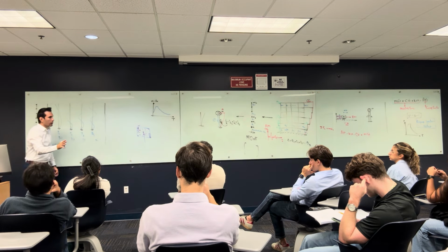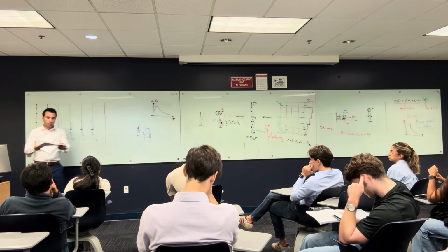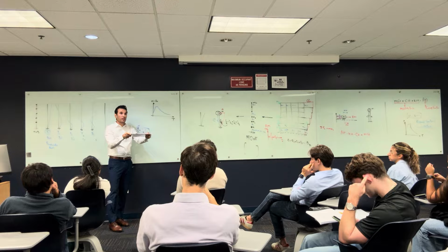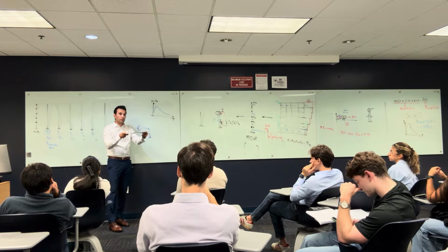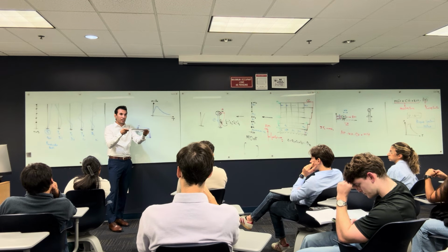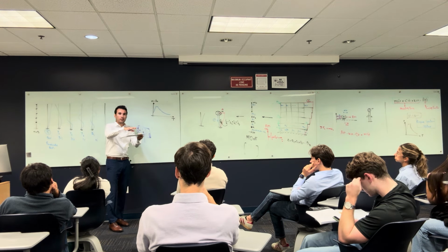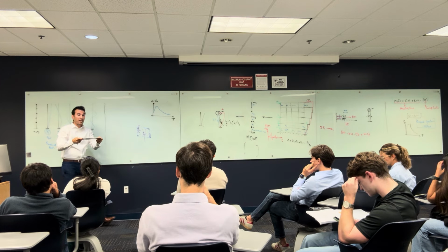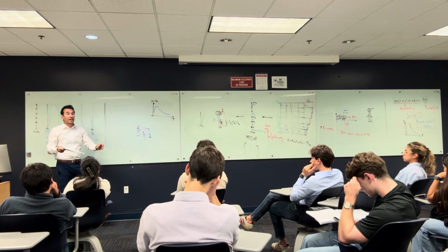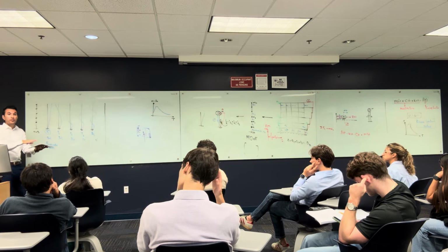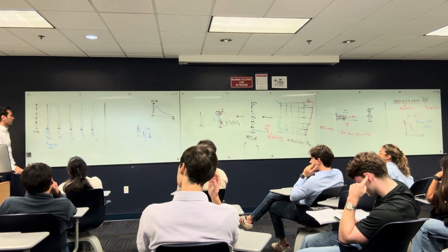And as I told you, usually when an earthquake happens or when a vibration happens in your structure, it's always looking for the weakest movement. You have a very strong element here, so this is the weakest movement. You cannot force your structure to move that way. It depends on how you organize the geometry of the shear walls and everything. So the torsion is gonna happen anyway, whether you like it or not. That depends on how you distributed the stiffest elements in your system.